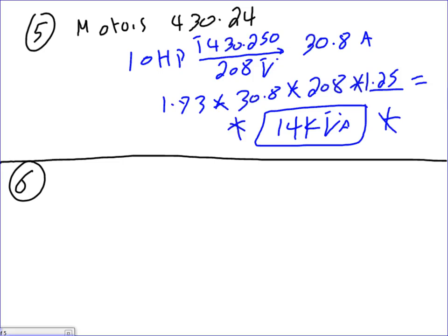Spencer, my friend, in load calculation, I always move with kVAs, always. So Holly's going to ask me, why didn't you add the amps, Chad, to the other amps and so forth? Don't you ever do load calculation based on amps, because a 30 amp 3-phase is completely different than a 30 amp 2-phase and completely different than a 30 amp 1-phase. Completely different. But if you put kVA, a 30 kVA 3-phase is the same as 30 kVA single phase is the same as 30 kVA 2-phase, guys.